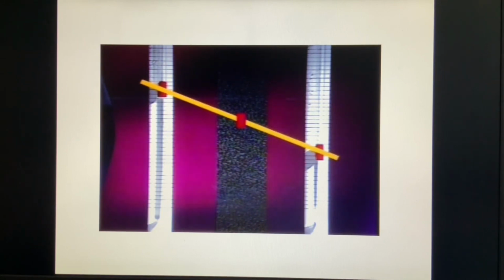If the pressure drop was constant, we would expect this tube's level to be here. Will that be the actual height, or will it be higher or lower? The water level in the center tube is lower than expected, showing the lowered pressure in the constriction.